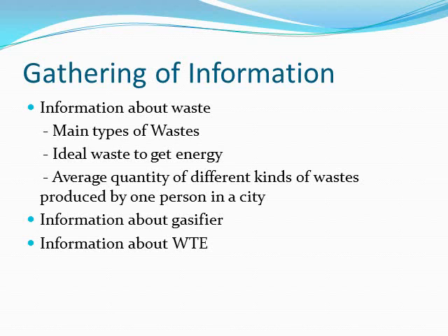For information of the waste, in order to do this research, I have to know the main types of the waste, which are mainly municipal solid waste, in short form MSW, commercial and industrial waste, in short form CIW, and the construction and demolition waste, in short form CDW. The ideal waste to undergo waste to energy conversion is also essential to know. After reading the references, I know that the ideal waste to get the energy is a waste with high calorific value, low moisture content, low inorganic content, low contents of sulfur, nitrogen, and chlorine, low volatile components, and so on.